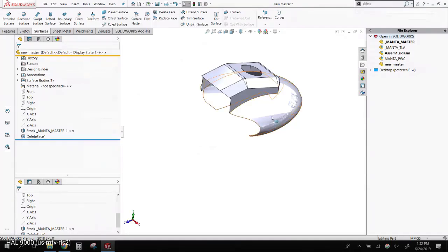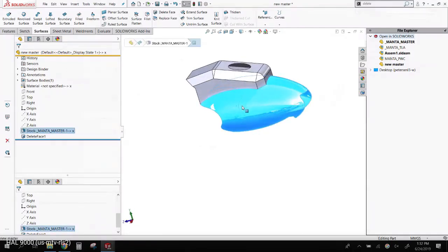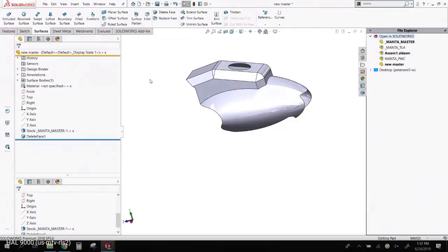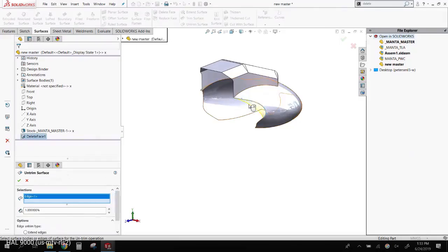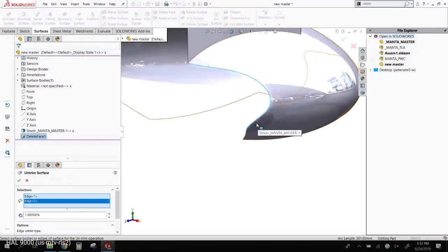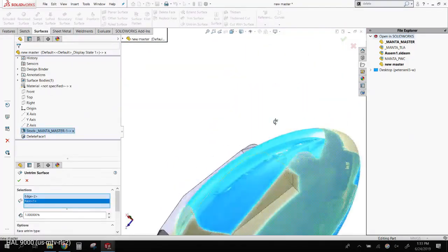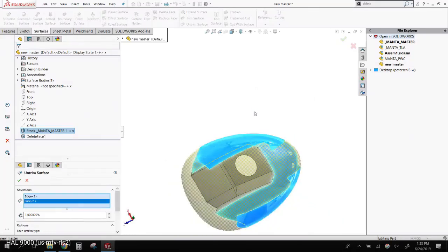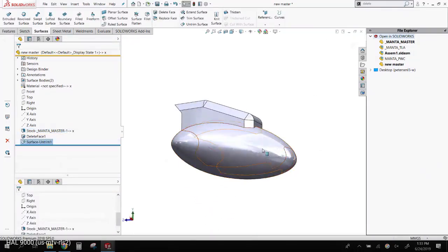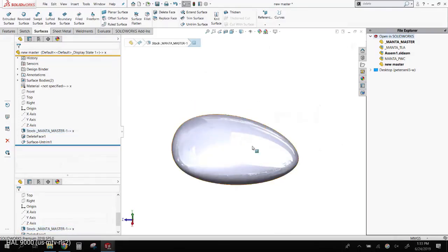When you have a surface like this where things have been extruded through it and now the face, you know, I'm missing a bunch of what the original surface had in it. There is a tool called Untrim. If I try and do edge by edge, I'm not going to get anywhere. But if I pick the entire face, it takes a look at it. And if it's able to extrapolate what that surface should look like, it'll put it back. So Untrim's a pretty crazy command. So now I've got that whole piece.